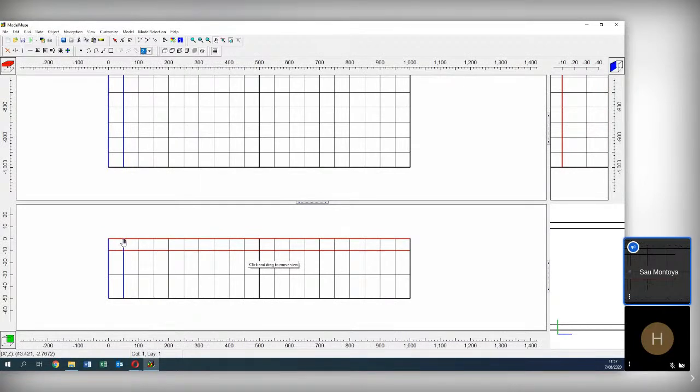Here, for example, this will be sand, this will be sand, and this will be clay. The hydraulic conductivity of the sand will be maybe 5 orders of magnitude bigger than the clay. So the flow actually happening on the clay layer will be minimal. Will be, how is the word? I don't remember the word.